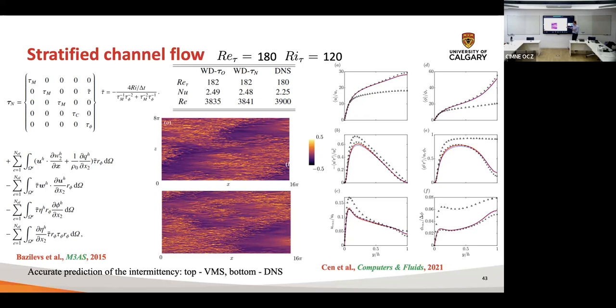So you can see your turbulent quantities change quite a bit, okay? And here we're looking pretty much at the blue and red line, okay? We will also explore a different definition of the tau, because when you deal with stratification, the Boussinesq term in your momentum equation triggers a coupling between the vertical component of your momentum equation and the advection diffusion equation.